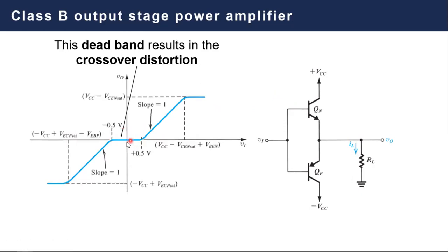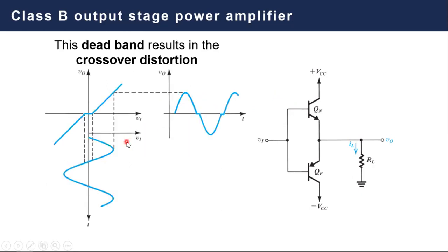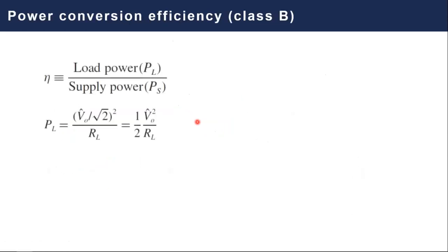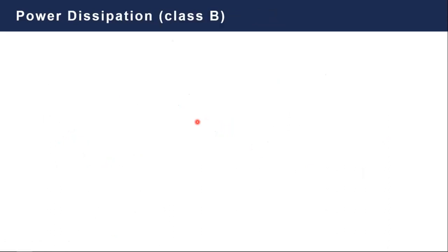So this opens a problem related to the distortion that can occur in your output voltage with respect to the input, due to the discontinuity in the signal crossing zero. As a modified step, we propose some alternatives toward getting rid of this dead band.